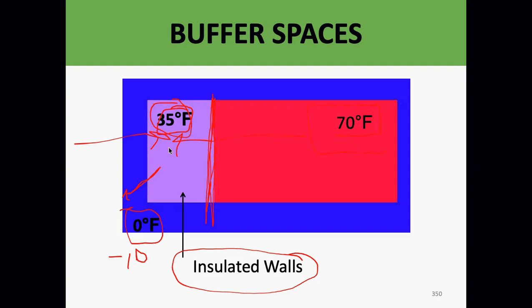I guarantee you, if you're working in this type of environment where attics freeze, you're going to want to carry a roll of the electric pipe warmers that you can wrap around the pipes. You're going to want to always have a roll of that in your truck, because every single winter you're going to follow the installation team around and end up wrapping the condensate pipes, because they will freeze and it will cause no heat situations.